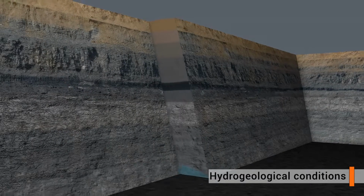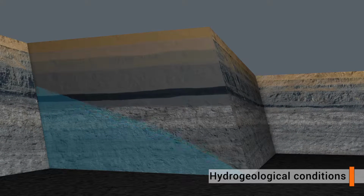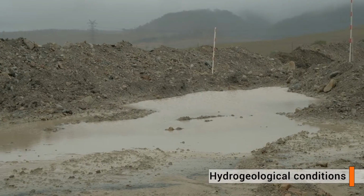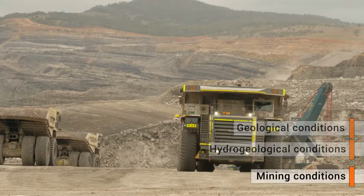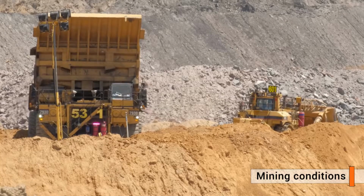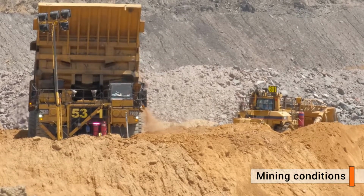Hydrogeological conditions contributing to failure include an increase in water pressure as a result of groundwater flow or blockage of groundwater flow behind the slope face, and ponding of water on the crest or at the toe of an excavated or dumped slope. Mining conditions or practices contributing to failure include dump tip heads formed from highly weathered or saturated waste material.